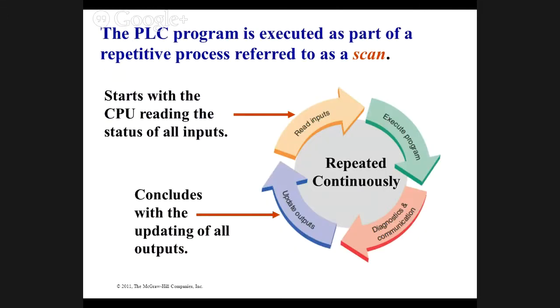Now, we're going to talk about scan time. The PLC program is executed as part of a repetitive process called a scan. It starts with reading the inputs, execute the program, diagnostics and communications, and then it updates the outputs. We sometimes forget about diagnostics and communications, but basically: read the inputs, execute the program, update the outputs.